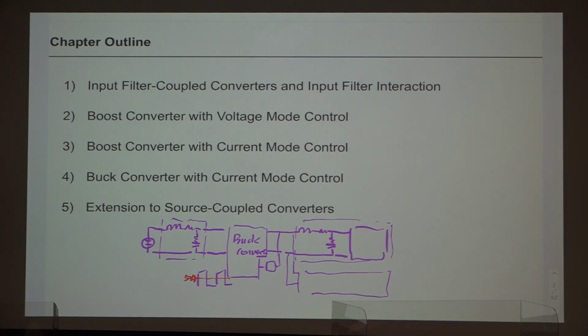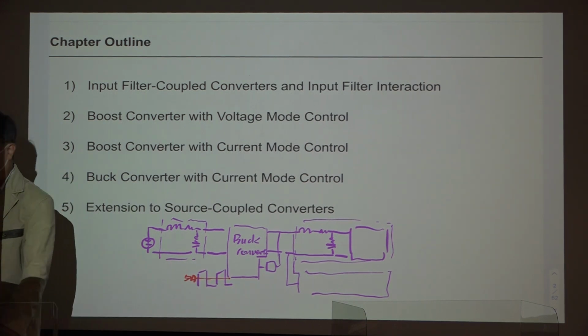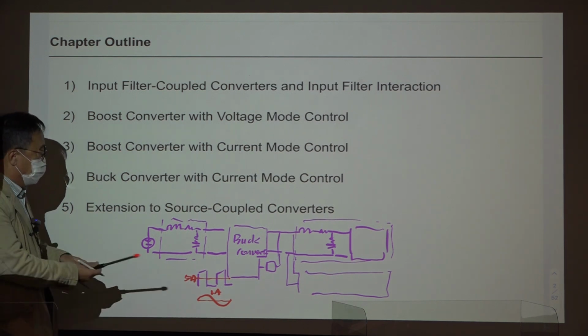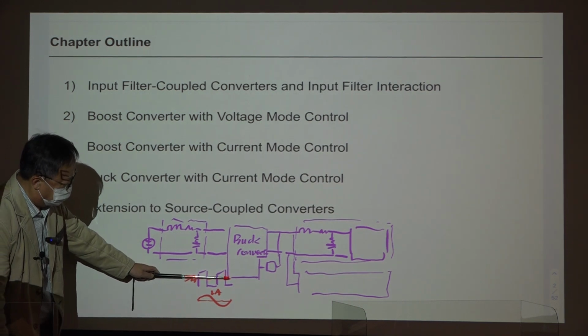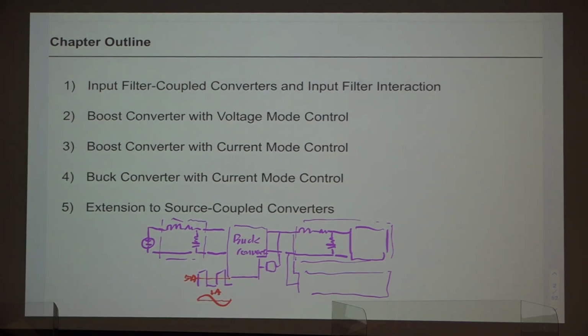Then the fundamental component of this at the switching frequency, not line frequency, can be 10 kilohertz, something like that. And the fundamental component of this is around 1 amp in general. It depends on the duty ratio of this converter, and usually maybe 1/5 of this average value. That will be the first component, and the requirement is that this fundamental component of the current coming from the input side should be very small.